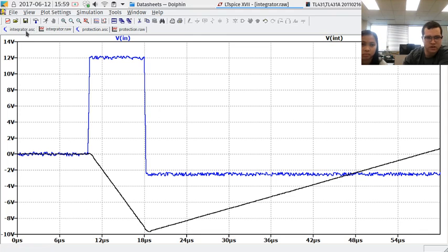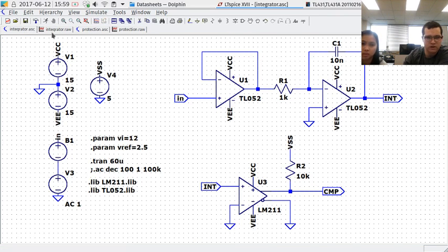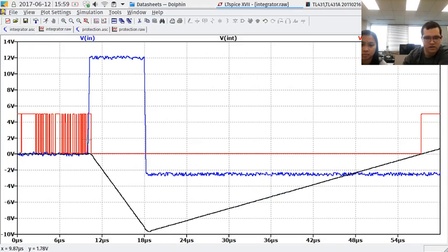But anyways, one more thing to show here is the output of the comparator. Now, there's a lot of noise here, and we experimented some with using hysteresis in the simulation, but we've designed the digital circuit in such a way that this noise is actually not a problem, because the output of the comparator is only measured at this point here and at the end here, or actually during this full discharge cycle here.